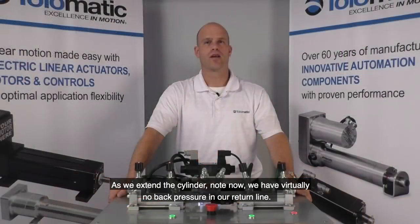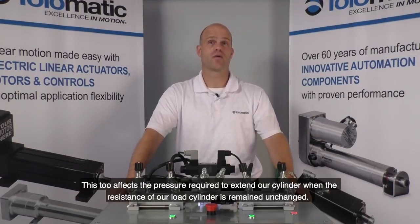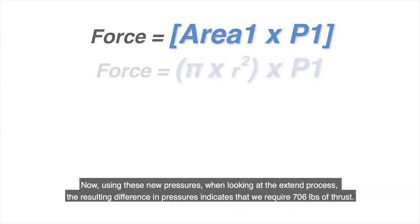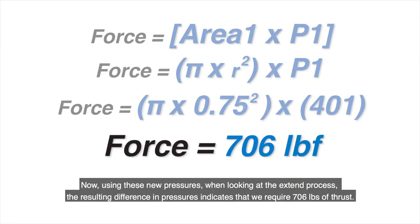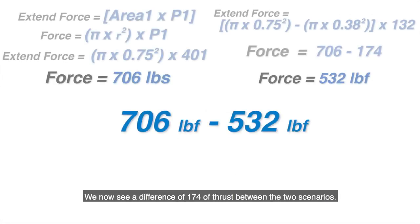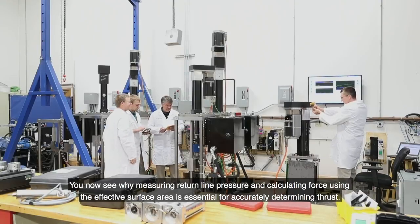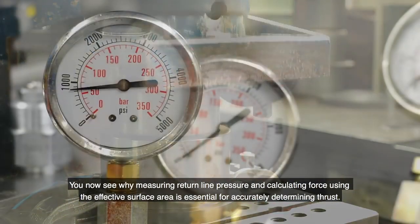As we extend the cylinder, note now we have virtually no back pressure in our return line. This too affects the pressure required to extend our cylinder when the resistance of our load cylinder remains unchanged. The same is noted during the retracting of the cylinder. Now, using these new pressures, when looking at the extend process, the resulting difference in pressures indicates that we now see a difference of 174 pounds of thrust between the two scenarios.